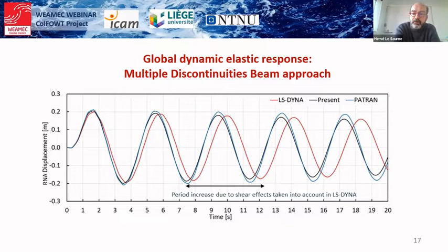So we see that our model correlates almost perfectly with Patran results, but we observe some discrepancy on the response period with LS-Dyna. And this discrepancy is due to the fact that shear effects are accounted for in the LS-Dyna calculation, but not in our model, because for the moment we have considered only the Euler-Bernoulli theory. But we can, of course, extend the model to Timoshenko beams and take into account shear effect and rotation inertia.